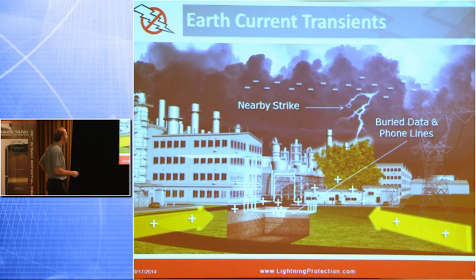Maybe it's a Bailey Control, Foxboro, Honeywell DCS, and we're communicating with some instrumentation controls in the field. That communication is done via buried cables in either conduit, raceways, or what have you. Well, remember we talked about the fact you had positive charge on the upper portion of the thunder cell, negative charge on the base of the cell. We're inducing that positive charge on the earth's surface. Those buried cables are immersed, surrounded by that positive charge.